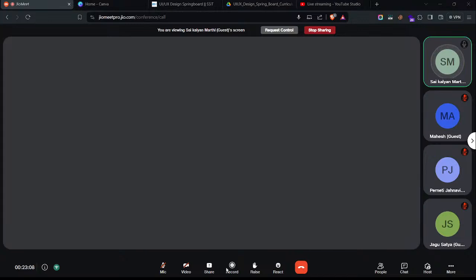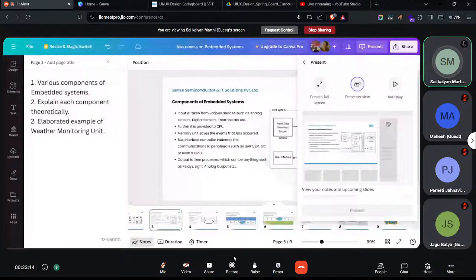Now the system has requirements, and we need to divide the hardware and software developments. This is the critical part in any system development. We will have a requirement like monitoring CO, but to monitor CO we need a particular sensor, a particular interface to program, and particular hardware to develop for communicating with that CO sensor. So how are we going to divide the hardware and software requirements?